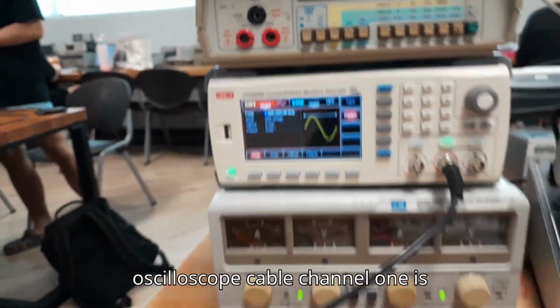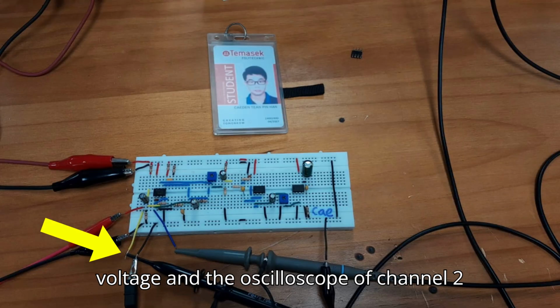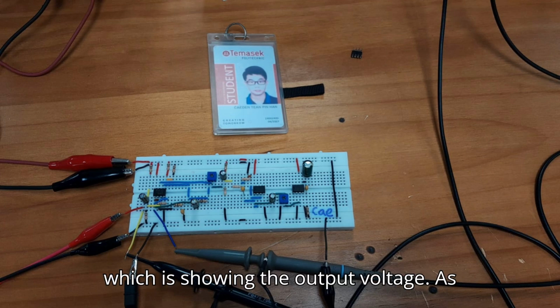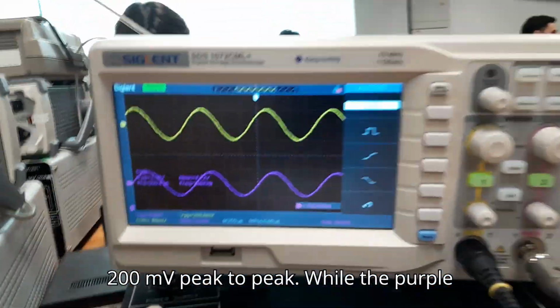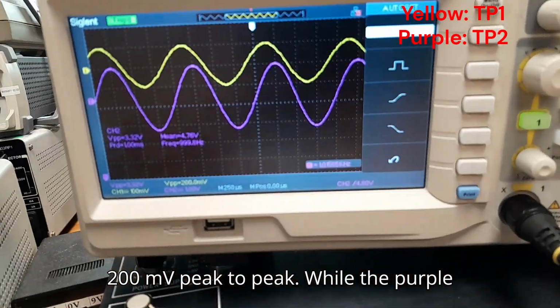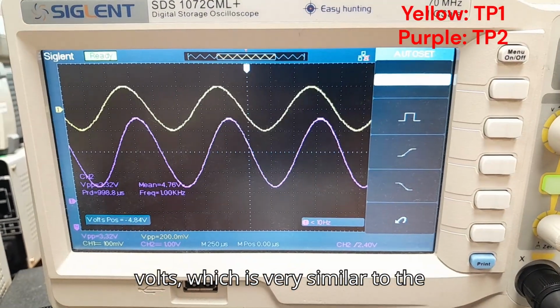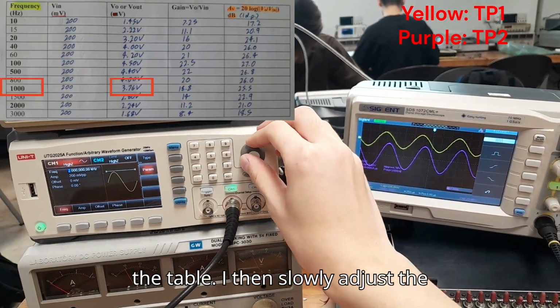The oscilloscope cable channel 1 is connected to TP1, measuring the input voltage, and the oscilloscope channel 2 is connected to TP2, which is showing the output voltage. As you can see, the yellow graph has a VPP of 200 mV peak-to-peak, while the purple graph has a VPP of 3.32 volts, which is very similar to the voltage shown under the Vout column for the table.